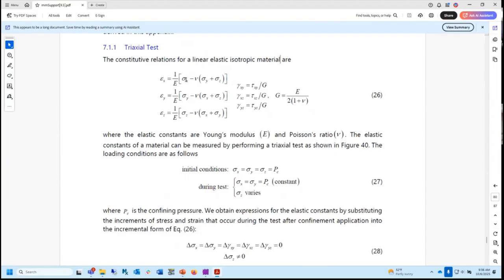And these are the stresses, sigma x, sigma y, sigma z. These are the shear stresses, tau xy, etc. There are 6 stresses and 6 strains, and those tensors are symmetric. And so we talk about E and nu. Here they are, E and nu. So this is the relationship between stress and strain for the whole entire system.